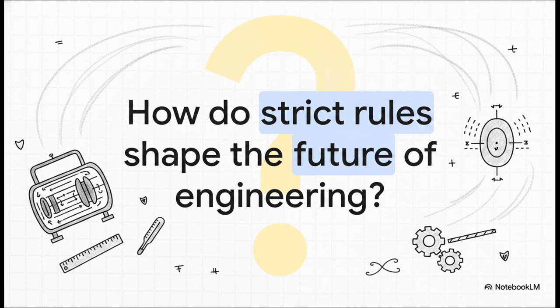Wow, we've covered a massive amount of incredibly precise ground today, haven't we? From maximum inside diameters and 30-minute hydrostatic stress tests to exactly 1/16 of an inch of mandatory corrosion buffering, all the way to the rigid legal boundaries for anode placement. It leaves us with a pretty provocative thought to chew on. When every fraction of an inch and every degree of heat is so deeply legislated by standards like TEMA, how do these strict, shared responsibilities between the buyer and the builder shape the true future of industrial engineering?